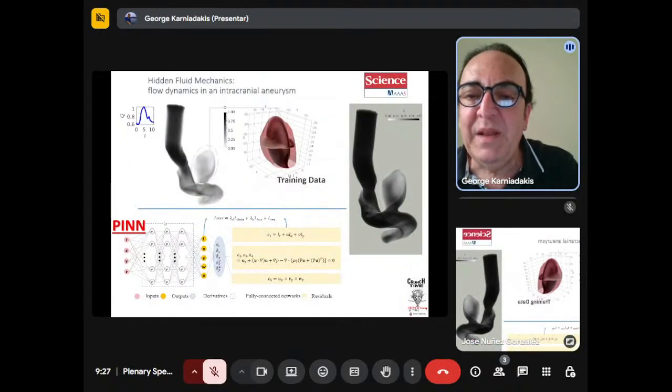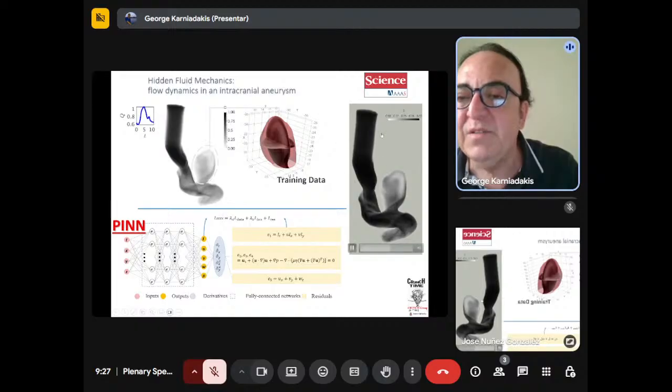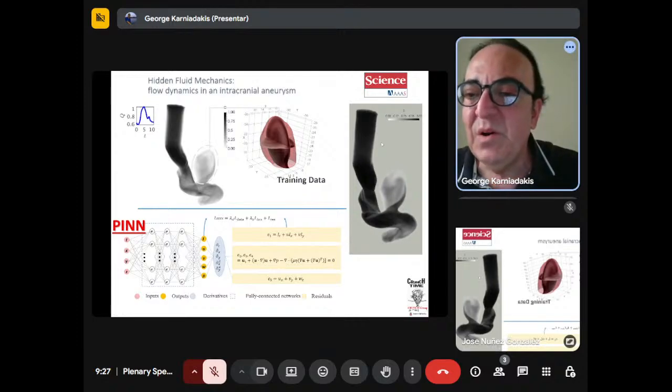I go to biomedicine now, biofluids. So again, on the right you see the picture that the neurosurgeon would see. It's a black and white video of the contrasting agent, the tracer. So what we do is we write an equation corresponding to what we see. Here we write for the intensity, which we consider a passive scalar, so we write an advection equation. We omit diffusion here. The model for the flow field is a non-Newtonian fluid because we want to account for nonlinear effects.